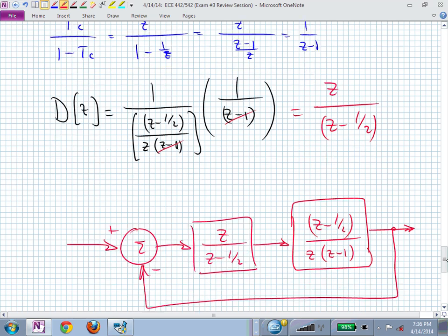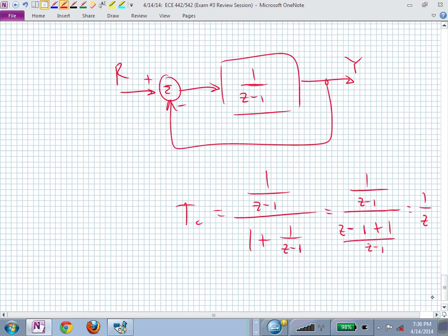So now what I'm saying in the closed loop is I want my output to be equal to my input with one sample period delay. That's my closed loop behavior, correct? So the question was, what do I do with my actuators? We've glossed completely over that, haven't we? We haven't worried about anything very physical in this design. So I had a G of Z that was incorporating all of my system dynamics.